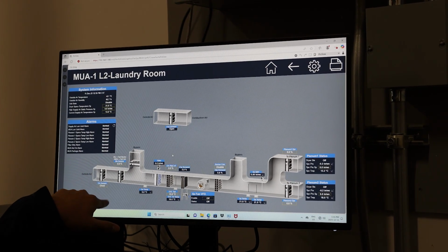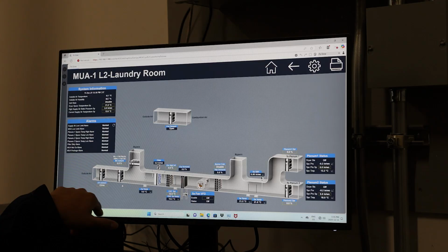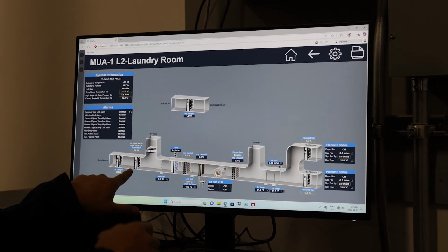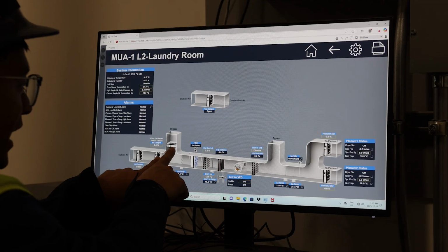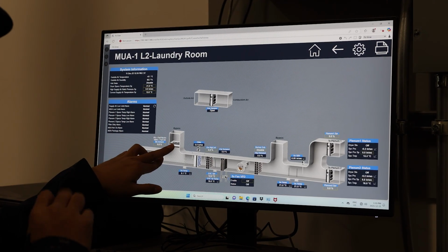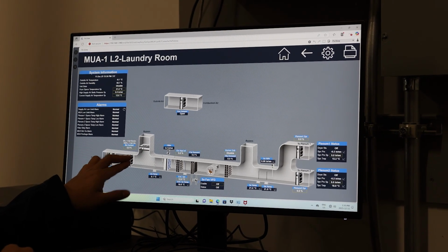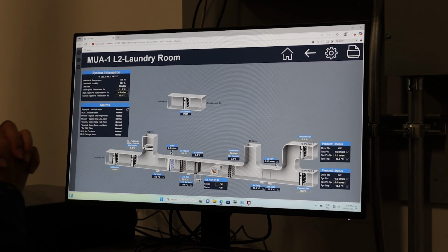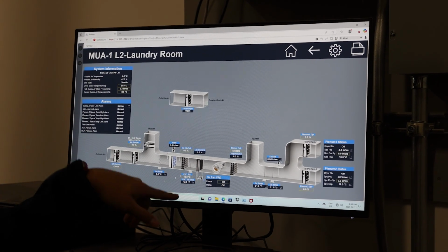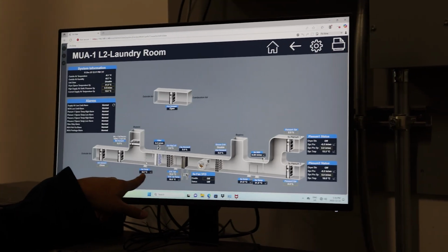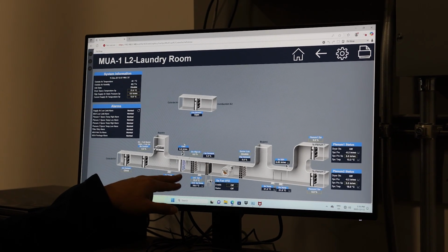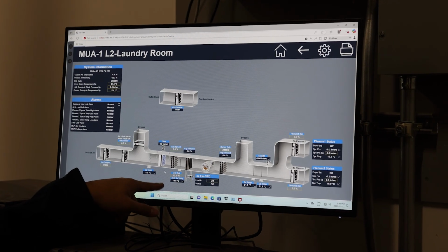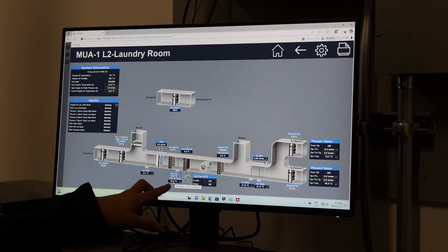And then makeup air unit, we have outside damper. This is our BMS damper. We will control the damper. Those 2 dampers are internal. It's the unit internal damper. So this damper needs to fully open before they turn on the fan. It's just a package unit. It comes with the unit. And then we have outside temperature sensor from the unit. Then we also have a filter. Monitor the filter differential pressure. And there's electric heater. After electric heater, we have a supply temperature.